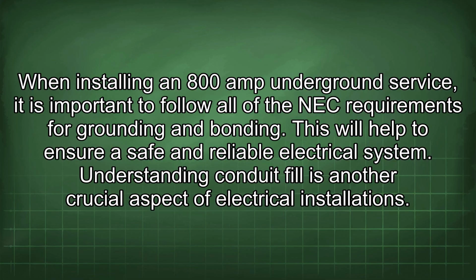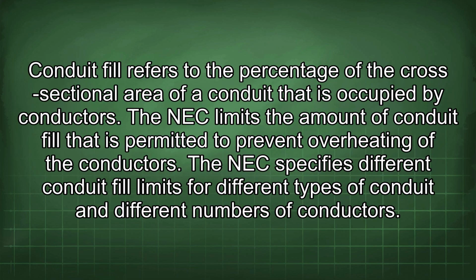Understanding conduit fill is another crucial aspect of electrical installations. Conduit fill refers to the percentage of the cross-sectional area of a conduit that is occupied by conductors. The NEC limits the amount of conduit fill that is permitted to prevent overheating of the conductors. The NEC specifies different conduit fill limits for different types of conduit and different numbers of conductors.